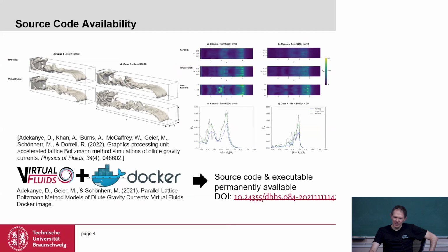Okay, so one thing that I also want to highlight is that if you want to install VirtualFluids, there are a few dependencies, not too many, but you need MPI, you need CMake, and you need Git. So these are the minimum requirements. And you need to understand and correct our mainly, maybe not completely correct installation guide. You have it a little bit simpler if you use Docker images. We provide Docker images where everything is already installed.